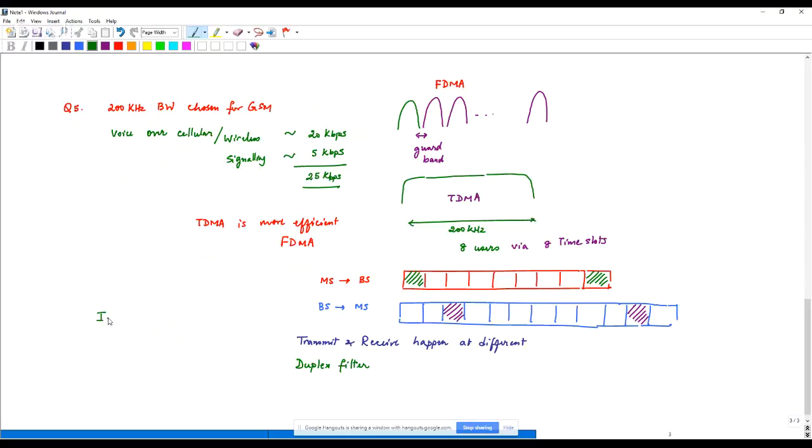So during idle time slots, what you do is measure neighboring base stations. And the reason you measure neighboring base stations is so that you can do handoff. In case you become far away from your own base station, measure neighboring base stations, and it is specifically for handoff. Now notice a system like FDMA cannot easily do that because it is transmitting all the time. It does not have idle time, whereas a GSM system naturally takes care of mobility. So you have a lot of time to go in and do measurements, and therefore this is one of the reasons why we want a GSM type system.